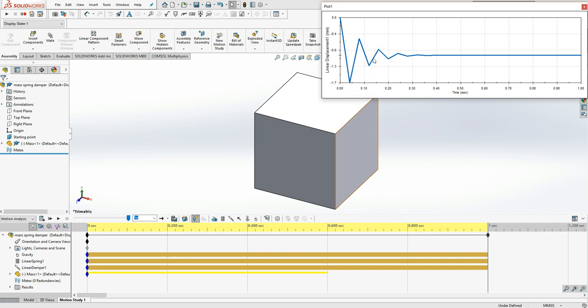This is an iterative process, in essence showing each time segment, each time section. Think of the first script that we did, where we were choosing a time step, choosing that iteration. SolidWorks is doing the exact same thing. These are the Adams solvers, by the way, and when we were using Simscape we used the Adams solvers. So this would instantly tell us the time step is too small.